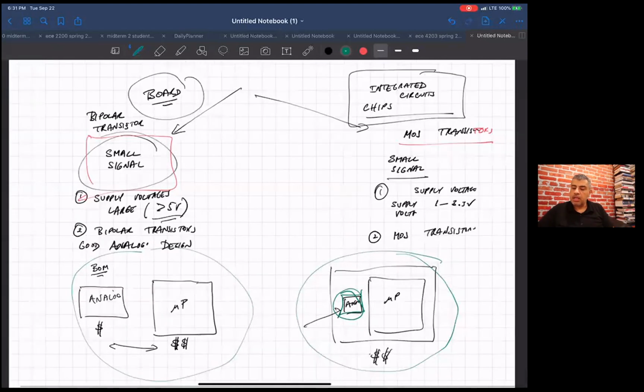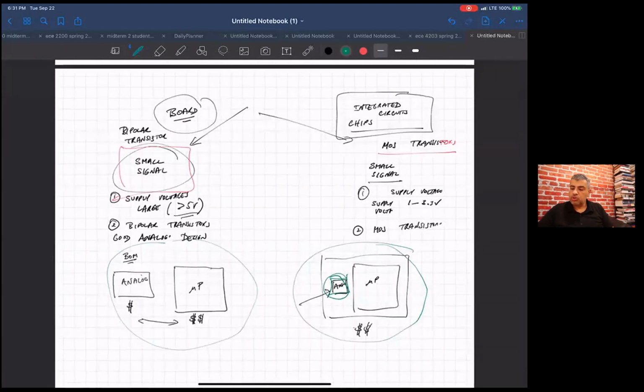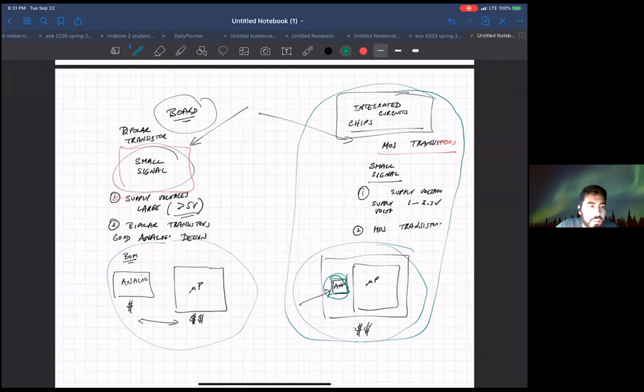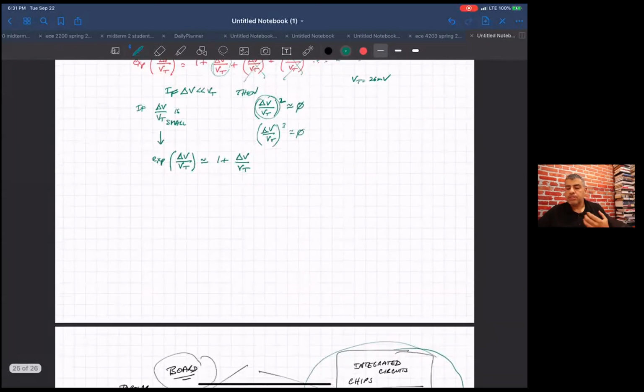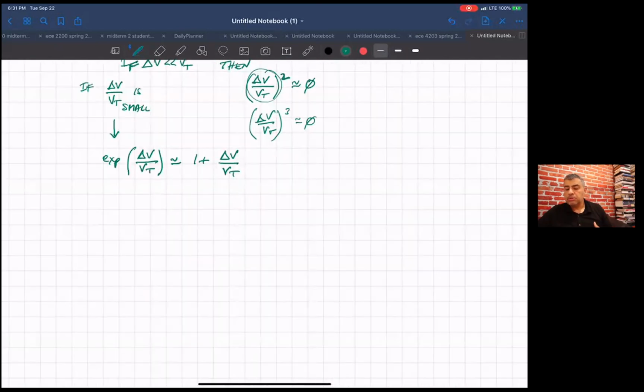This happens a lot when you start putting analog circuits into digital chips. If you're doing chip design, then small signal is just a good starting point, and it's just a starting point. Sorry, that was a really long answer. Even in the chip design that we do, small signal is still a good starting point, but you just can't stop there, is the unfortunate fact.